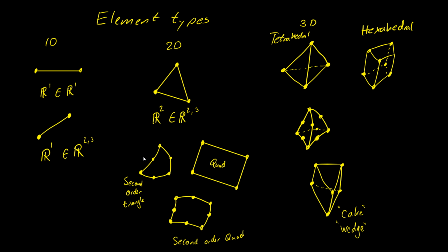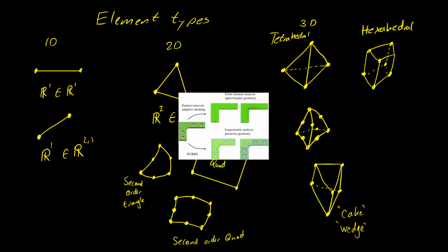And there's another side to that as well, a negative side, which is that these matrices become very, very spread out because there's no local support anymore. The support is much, much higher. So every basis function is affecting elements that are far away, and that's a little bit of a problem. It becomes sort of expensive to run it on one hand, but on the other hand, you need much fewer elements or patches because they are working with CAD patches to solve a problem using that.